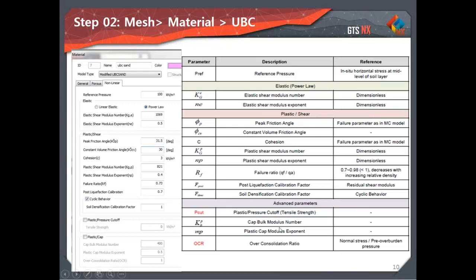As we had said, the program gives you up to 3 options to capture the plastic behavior. So this would be where you define those. These are optional, and you would activate these boxes here to give those values for the cap or the pressure cutoff options.